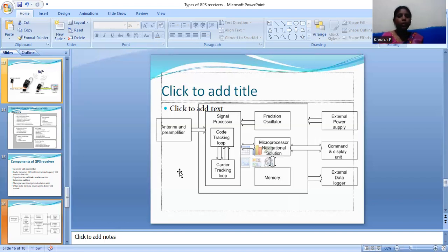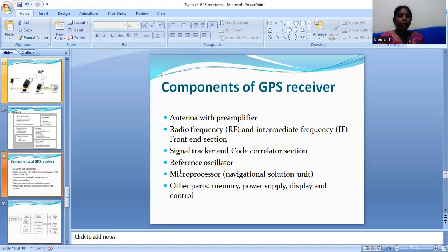So next one is electro-optical EDM measurements. Electro-optical EDM instruments are mostly used by civil engineers. The measuring length varies from 1 kilometer to 60 kilometers. As with the microwave instrument, all need line of sight conditions. The main components of instruments in this group are the light source, visible light produced by a tungsten lamp, xenon gas tube, and or laser light or infrared light, and a light modulator, with optical parts for transmitting and receiving the modulated light.